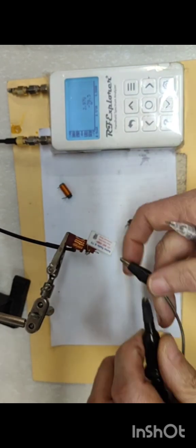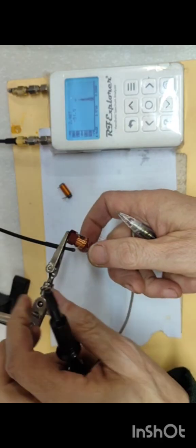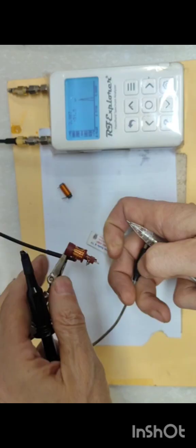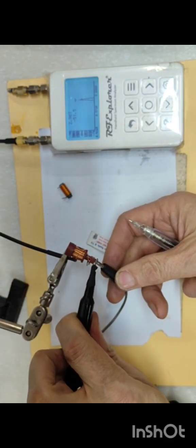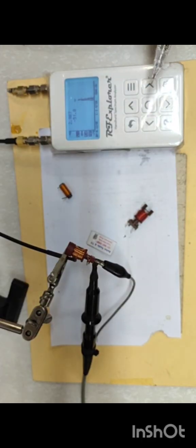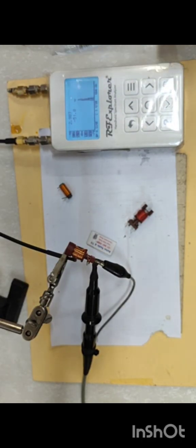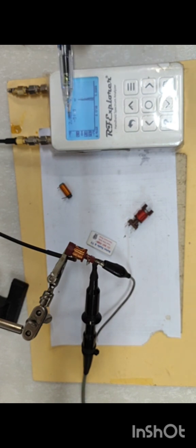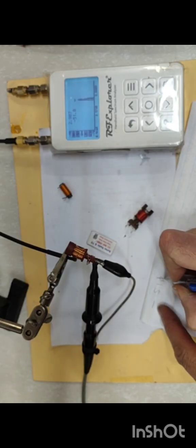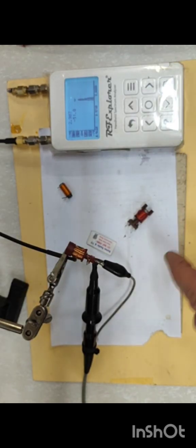Okay, now I'm going to apply, for argument's sake, okay, wait, let me just put this in properly. Okay, so it makes a good connection. And then I connect up the generator, and voila. Right now the spectrum analyzer is showing me 2.987 megahertz. Let me reset again one more time. Can you see over here? It will take a few seconds to scan over a period of time and pick up the highest peak. And right now, 2.98, okay, there it is. It picks up, and now it's going to lock. It has given me something like minus 51 dBm.